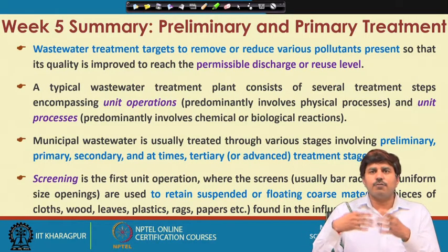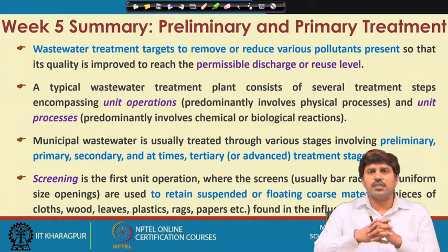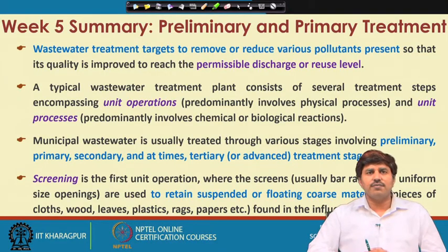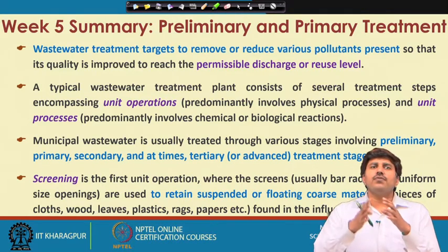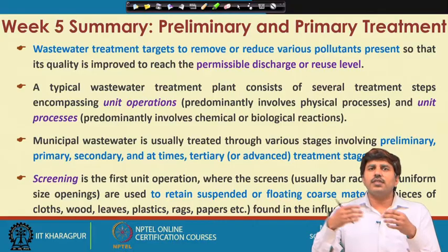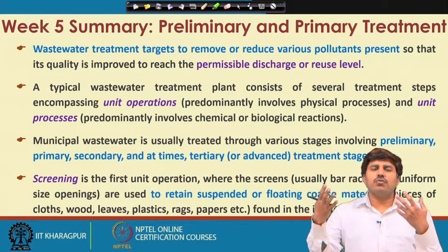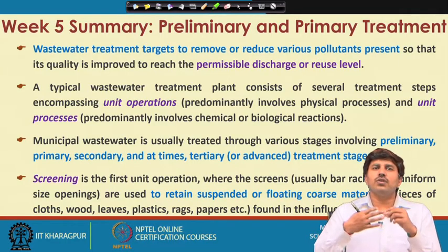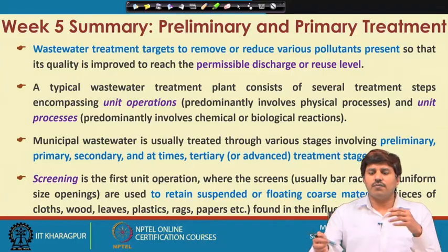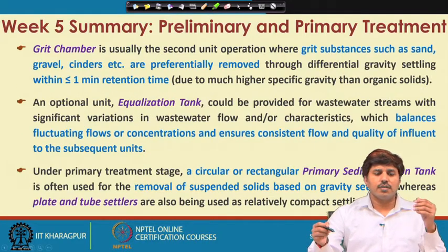There are other types of configurations available which were discussed in week 5 while discussing the screening process. These bar racks of uniform size openings are used to retain suspended or floating coarse material, which could include pieces of cloth, wood, leaves, plastics, rags, and papers, those kinds of things found in the influent water.